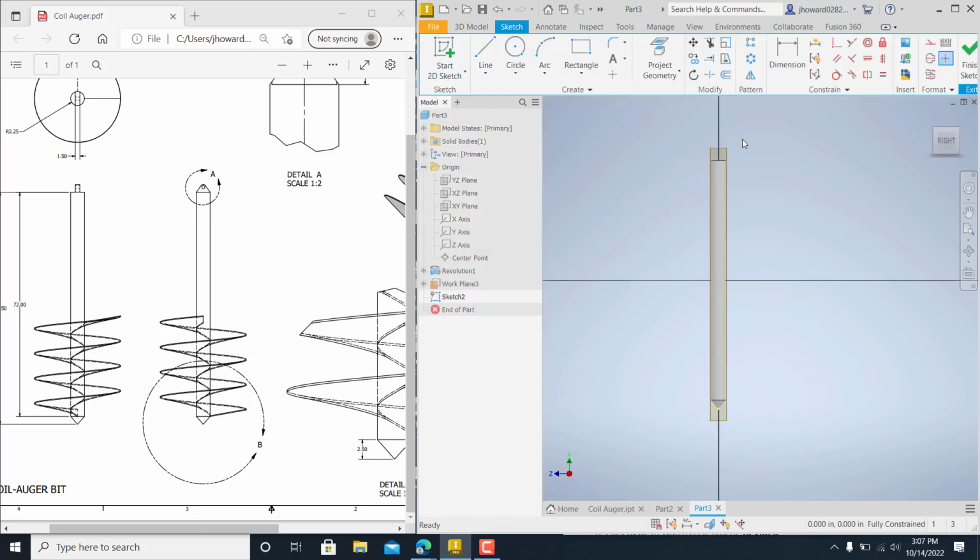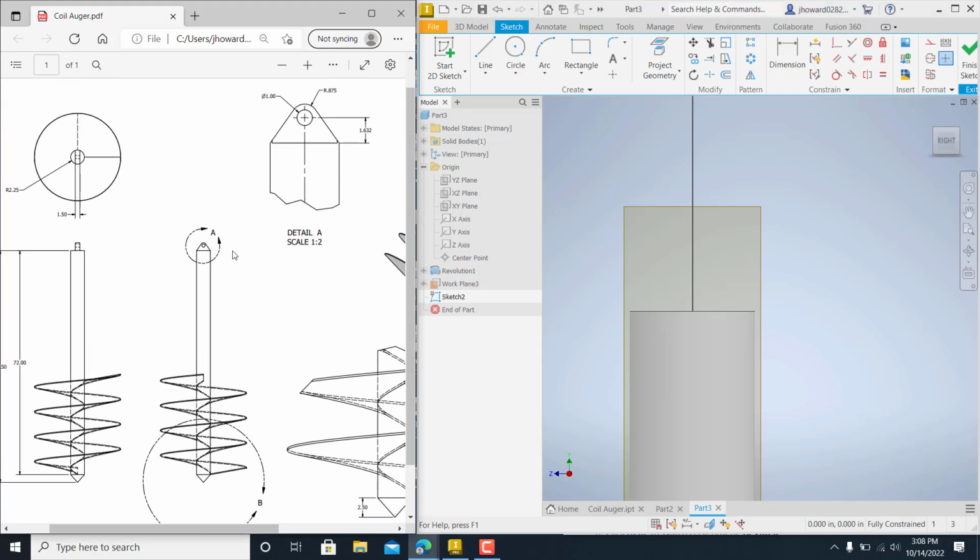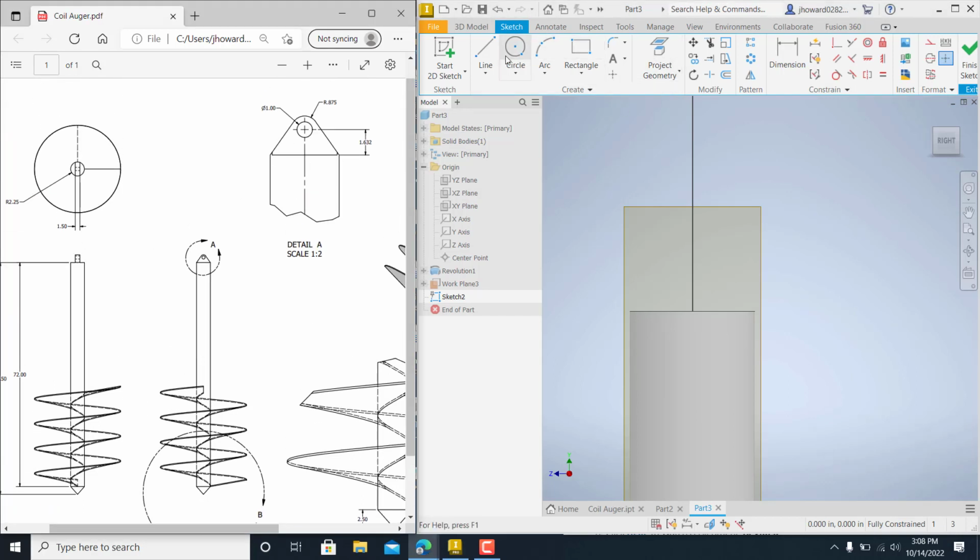So with that in there, I can go in here now, and you can slice that with F7, but for our purpose we don't really have to. But again, if I go up here and look, it's just coming off the sides. I got a circle here at 1.632, so I just come in here, catch it, and just come straight up with it.